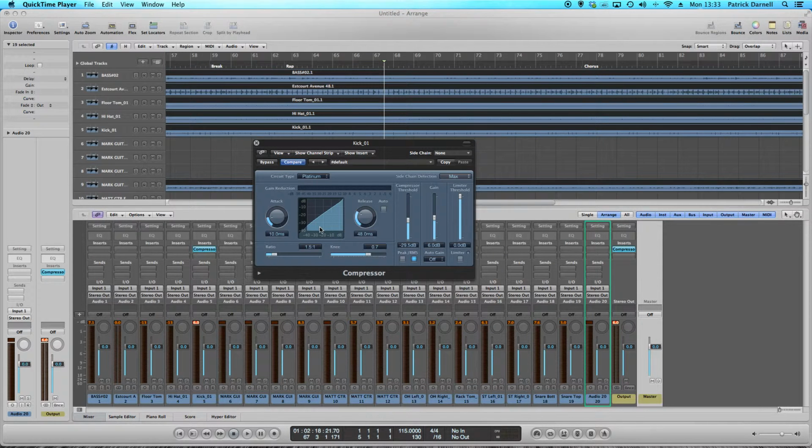By adding compression to a channel, the level of any audio coming in can be limited. This is especially useful in a live sound environment where a performer may be unpredictable. The compressor can be set to compress at a certain level, meaning that any signal above this level will be significantly reduced. This will remove the possibility of audio peaking and will also protect equipment.